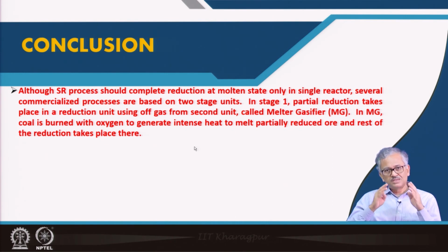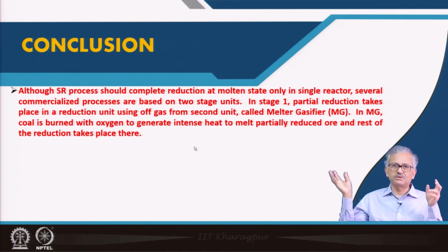But the major disadvantage of the ASR process is that unless you utilize the off gas effectively, the process will never be beneficial. Okay, so off gas utilization is a must. You have to generate the power that will sustain this process, as well as sell this power outside so that the process becomes much more effective.